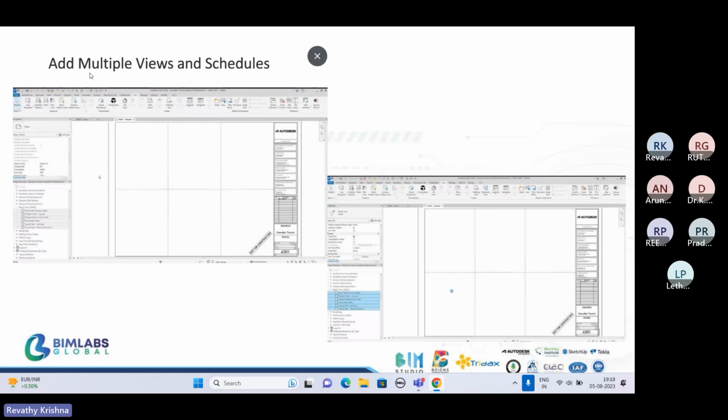Next update is add multiple views and schedules. In the previous version also, we can add multiple views, or multiple drawings, in a single sheet. Similar to this, in the 2024 version also, we can add multiple views. But the update is we can add the multiple views together. In the previous version, we have to draw the views singly. We have to draw a view into the sheet. After placing the view, we have to place another view. But in the latest version, we can simply select all the views which we want together into the sheet.